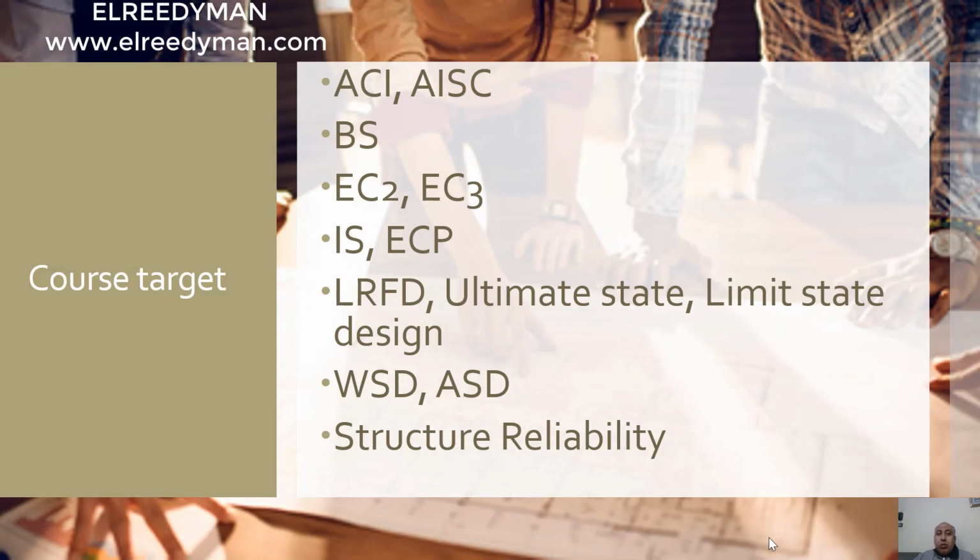Then we go through load resistance factor design, ultimate state and limit state design in the case of concrete itself, and WSD, working stress design, allowable stress design, and the concept of structural reliability. Or, by another name, we call it the structure's probability of failure, which we need to discuss now.